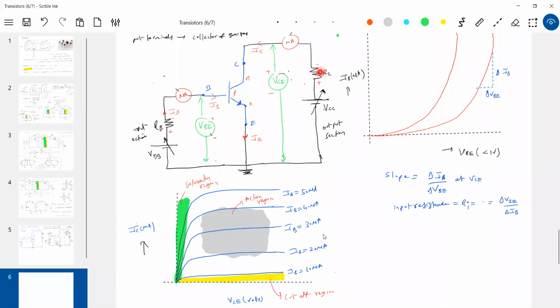These values. Therefore, these are called biasing networks. What they do is bias the transistor. They will make it operate in different regions by choosing different values of RC, VCC, VBB, RB. Got the idea, no? So now if you want to use it as an amplifier, adjust the transistor's values in such a way that it comes here. If you want to use it as an on-off switch, you should operate in these 2 regions.